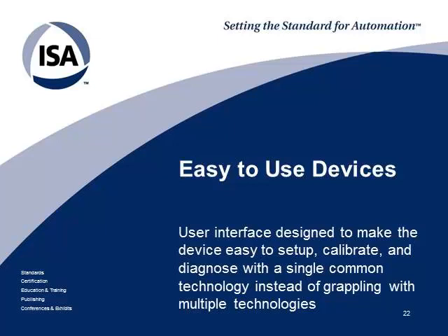You get this sort of plug and play, just like you put your USB stick in and hopefully it comes up and says, here are your files, grab them off. The same sort of concept applies to your field device, where you connect your fieldbus or your HART device to the network. You load it up onto maybe your handheld tool or your PC-based application. Hopefully your drivers are there. If not, you install your DD files, and then you have access to all those wonderful features that the device suppliers have integrated. And now we're talking about FDI because